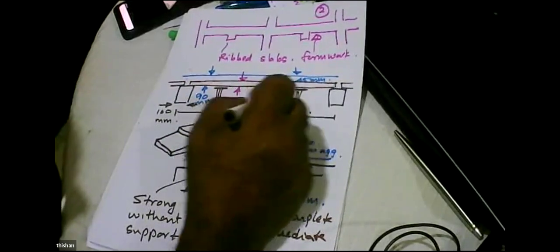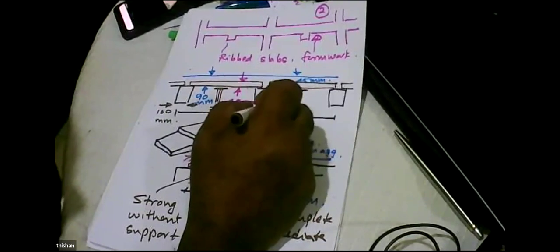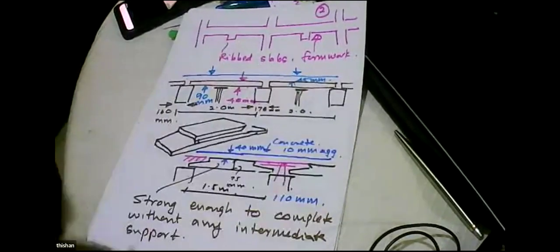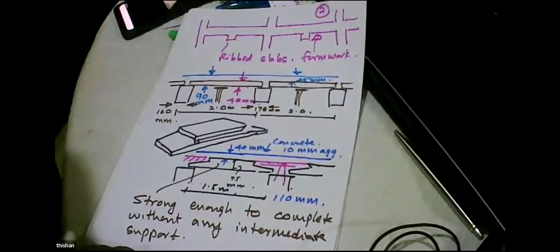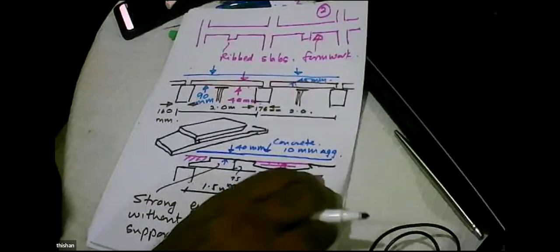Then we looked at the constructability. If you are going to cast this beam in situ, or precast it, but we have some lifting equipment like a crane or a tower crane to lift the beam, then the weight of the beam is not a major problem. So we thought, okay, let's do this. Considering that the beam will be cast in situ, we selected a width of 175.